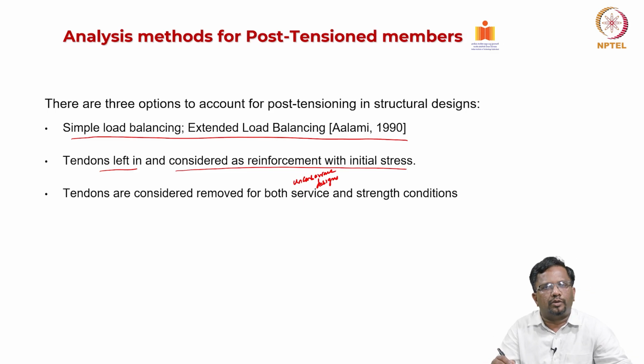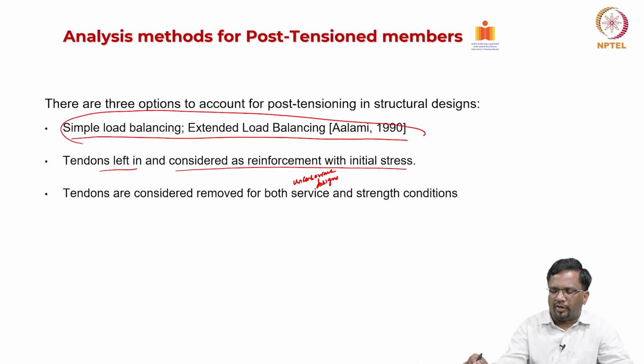So, typically it is not done. Sometimes the design officers, if they do not have the Excel sheets and want a quick conservative design, can do it like that. Also, if the PT provided is very small, just to ensure some uplift, then for a conservative design they sometimes ignore it, but the more common method is this load balancing concept.